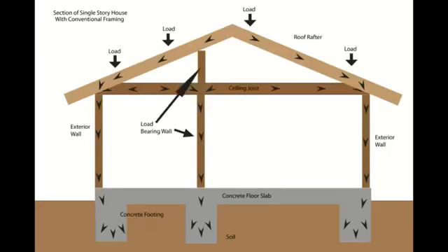Now here's something else you could run into, and that would be a load-bearing wall with another wall on top of it in the attic, let's say, supporting the roof. And here would be something where it would be supporting the peak of the roof or the ridge with some type of a bracing system. And if you had something like this, you poked your head up in the attic and you see this, there's a good chance you won't be able to remove the wall.